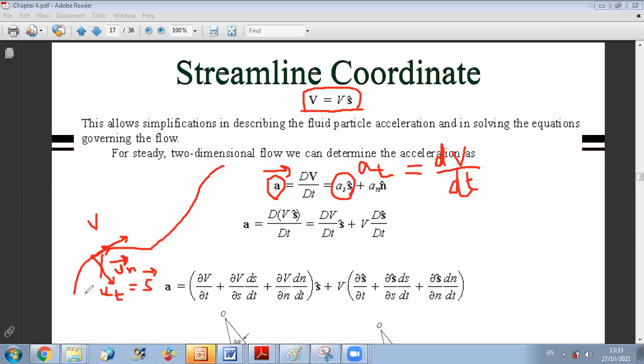On the other hand, whenever you have curved motion, automatically this will induce a component of acceleration along UN, because AN is the component of acceleration that will allow you to change direction. You cannot change direction without having a normal acceleration. And in dynamics also, you have demonstrated that AN is V squared over rho, where rho represents the radius of curvature at any location. If I want to illustrate it for you in this figure, for example, at this point, you can consider that when moving over this segment, I am moving on a circle at this instant, and I can define at this location a certain radius, rho 1.